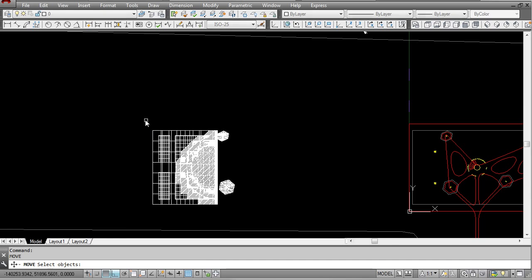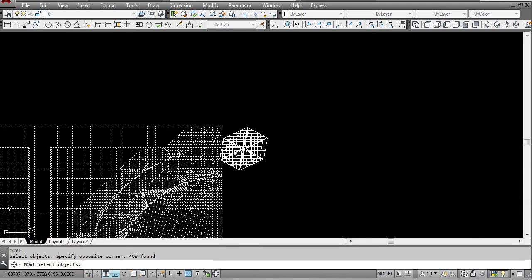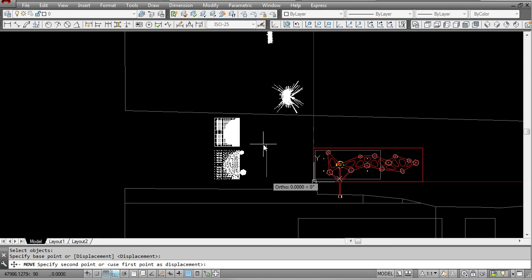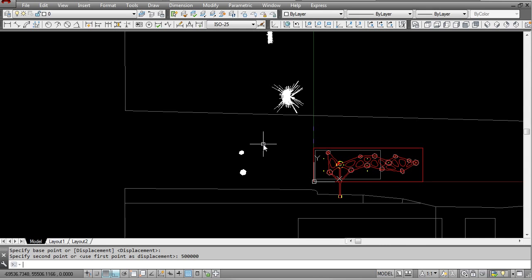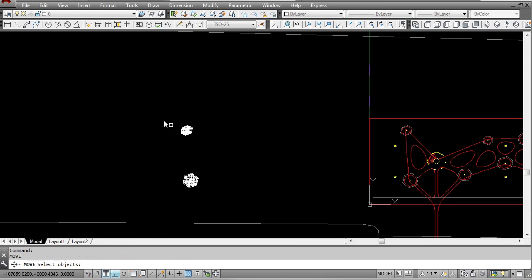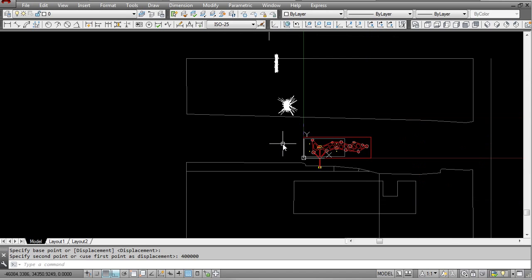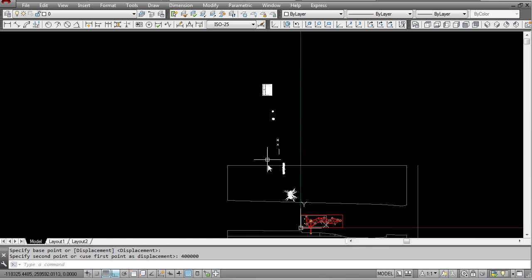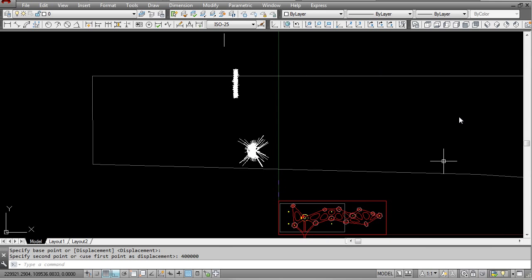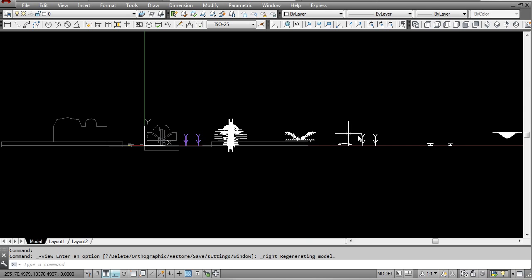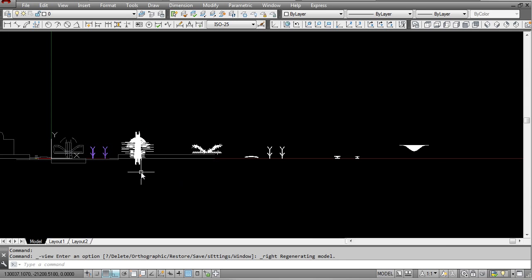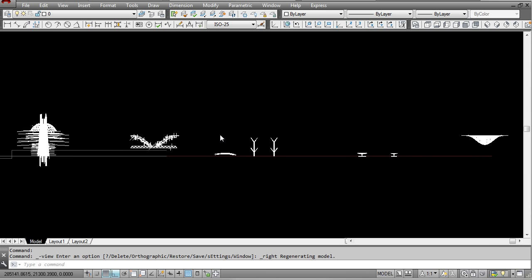And I'm doing this because I don't want them to overlap each other once I use the flatshot command. So you can see that the differences are quite big. It's all neatly spaced out at 100-meter increments. And this is going to allow me then to just bring it all back together. So once I go into my right view, I'm going to see all of these objects next to each other. I could also space them out slightly tighter, but I'm not that concerned about making that too efficient.